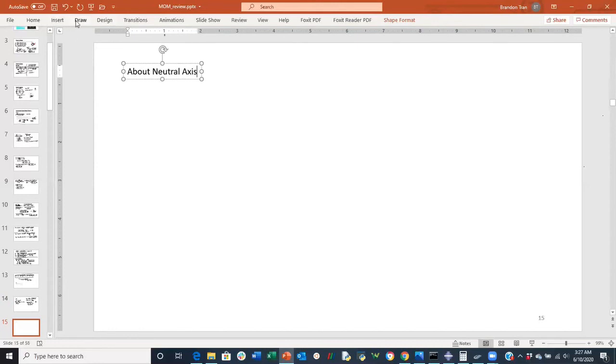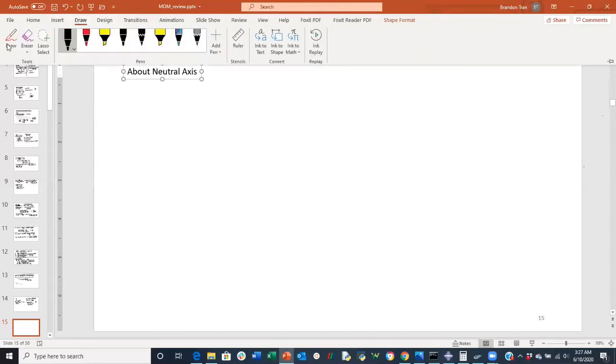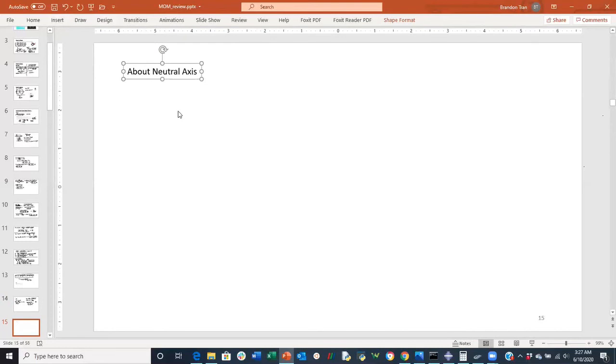So everybody knows essentially what the neutral axis is. If I have an arbitrary cross section like this again, with the z direction here and the y direction here, some angle will yield me an axis, the neutral axis, where on this axis stress is equal to 0.